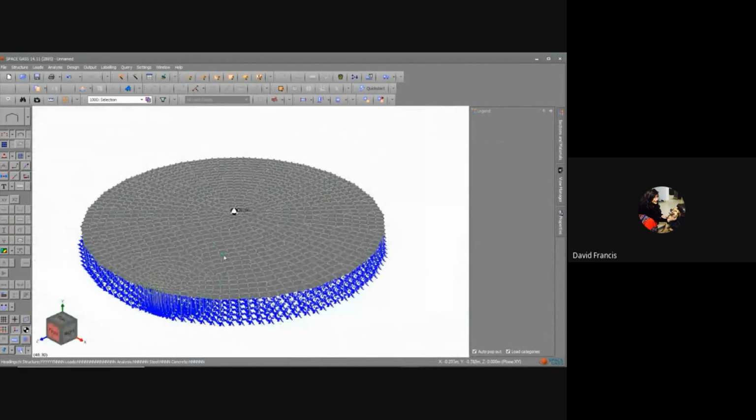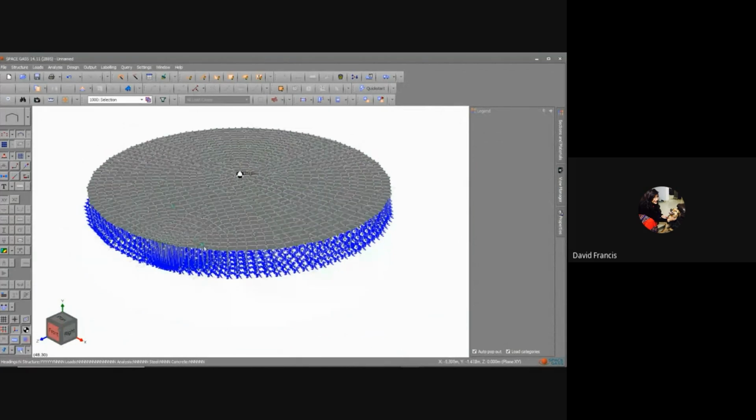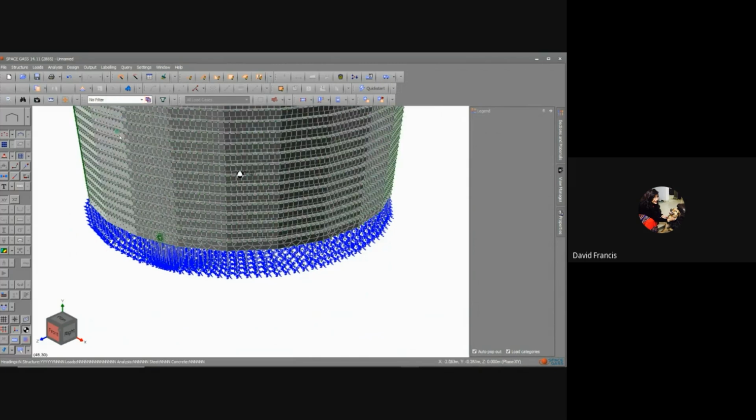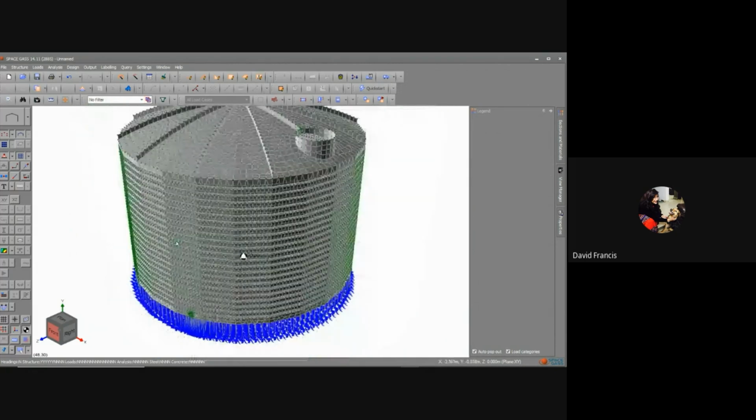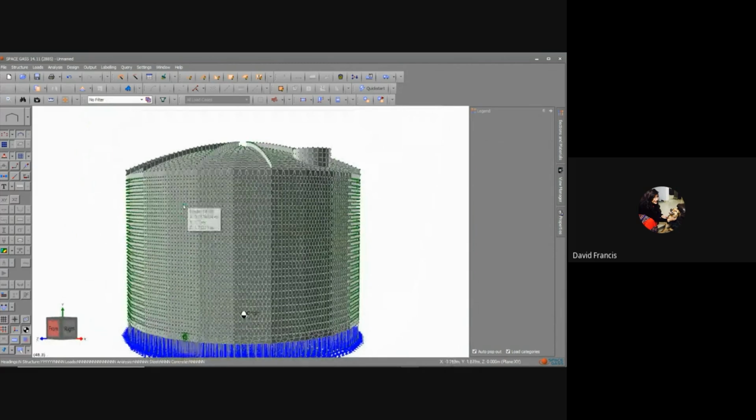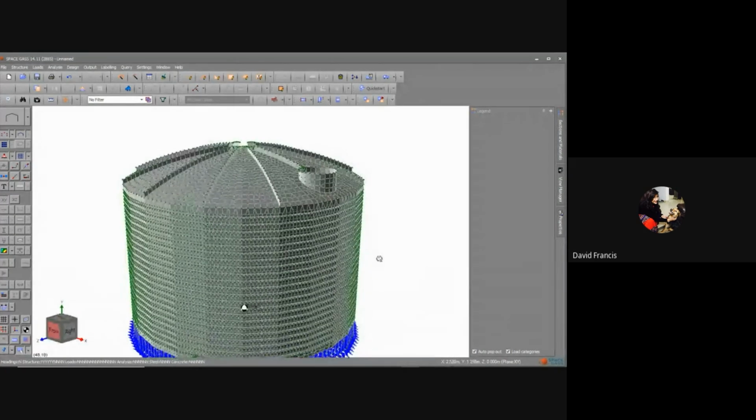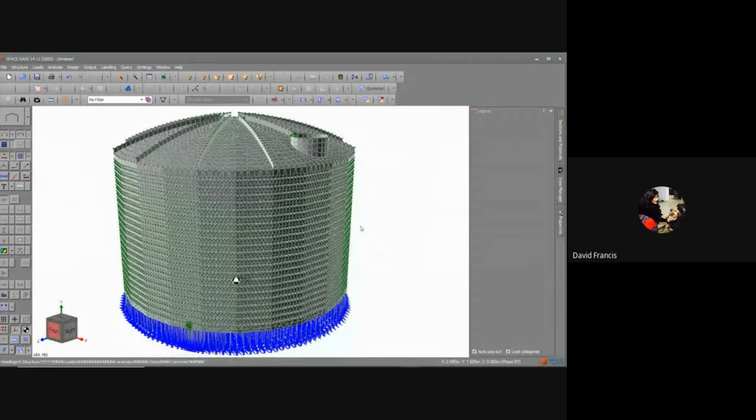Now I may want to apply some hydrostatic loading into the tank. If I go back to the fact that I've got part of the tank, currently it's using a 1000, which is a temporary filter, which was created by me when I selected what was being shown. All right, so now I'd go through the process of applying a load inside this tank. And it's going to be a hydrostatic load.